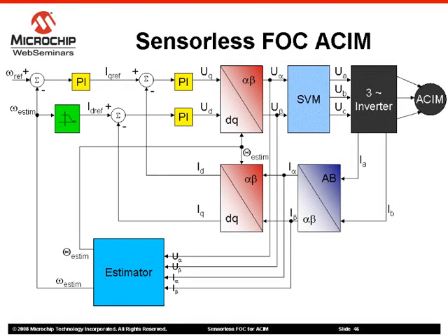The next block to be described is the PI controller block. The PI controller is the control loop feedback mechanism that corrects the error between the measured process variable and its reference value. In the case of induction motor control process, 3 PI controllers are used, one for each current component corresponding to magnetizing flux and the torque, and another one for the speed.